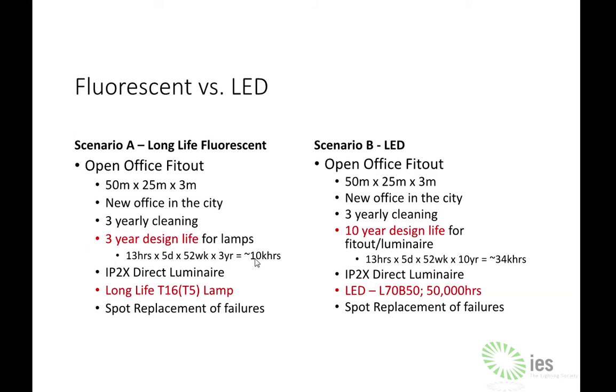So this one's only getting 10,000 hours per lamp, whereas when we start multiplying this one out, we're expecting to get 34,000 kilo hours out of this fitting. Still less than our L70 B50, 50,000 hours. It's not unreasonable.